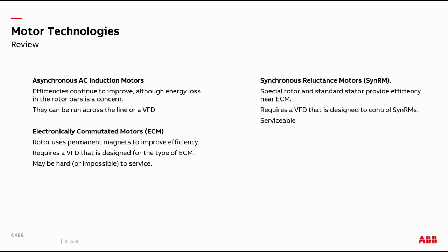Synchronous reluctance motors, or SynRM motors, have a special rotor and a standard stator, and this provides near ECM efficiency. However, it does require a VFD that's designed to control SynRM motors. Another advantage is that it's serviceable. Much like the induction motor, it can be serviced by your local motor shop.